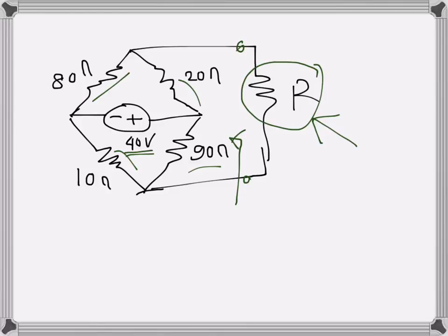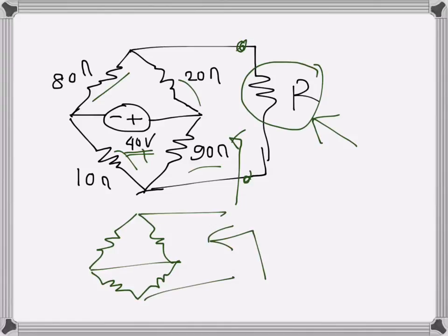So basically we now want to find the Thevenin's resistance as seen from here, and to do that we have to inactivate the active sources, making them dead. There is only one voltage source, the 40 volts, and we have to short circuit it. So this is our arrangement for finding the resistance as seen by R, let's call it R line, or R Thevenin.